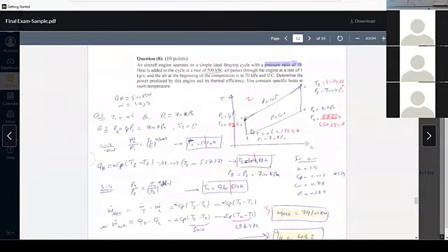So you need to make sure that at every state you have 2 pieces of information. You must make sure that you have at least the temperature. These in red are important. He gives you the inlet, which is 0 Celsius and 70, I think. Yeah, here, same as the final. So you have 0 Celsius and you have P1. And he compressed, so you have P2. And you already have isentropic, so you can easily get T2 or V2 from the ideal gas law. 2 to 3, you have constant pressure. So P2 is the same as P3.